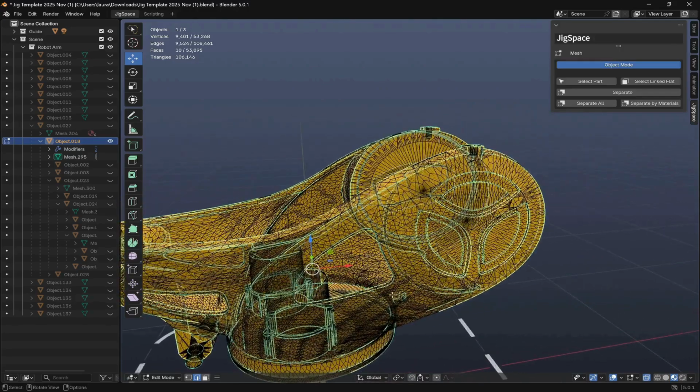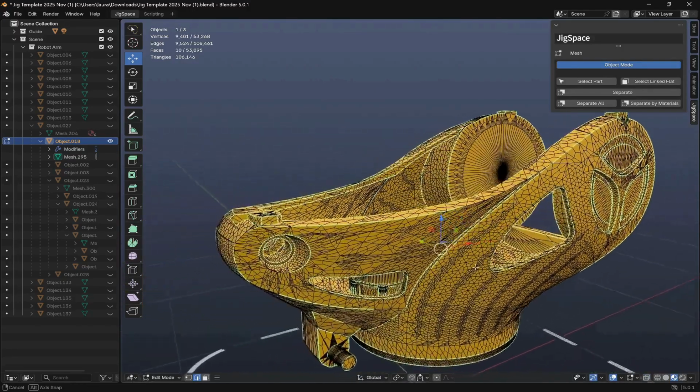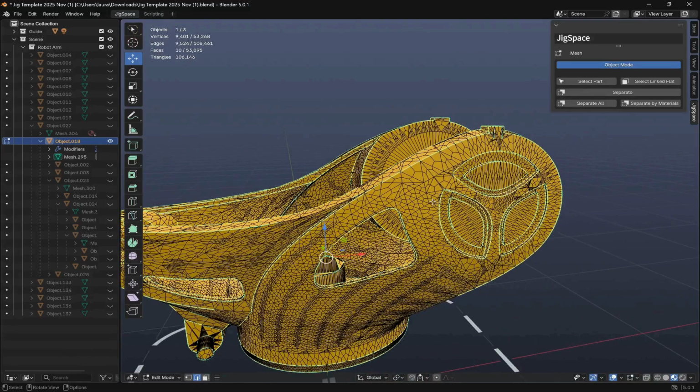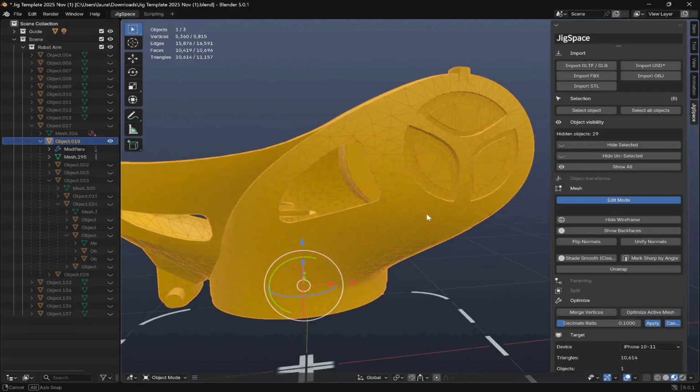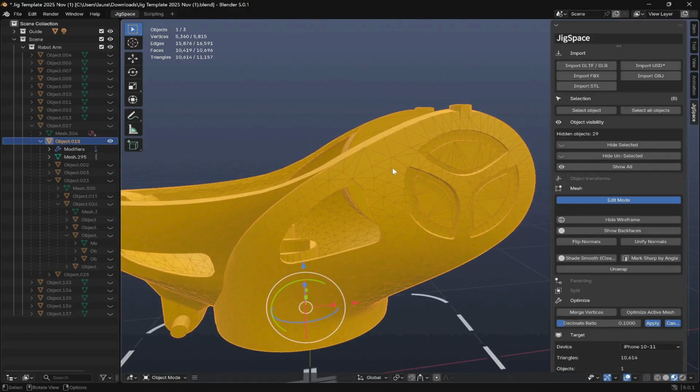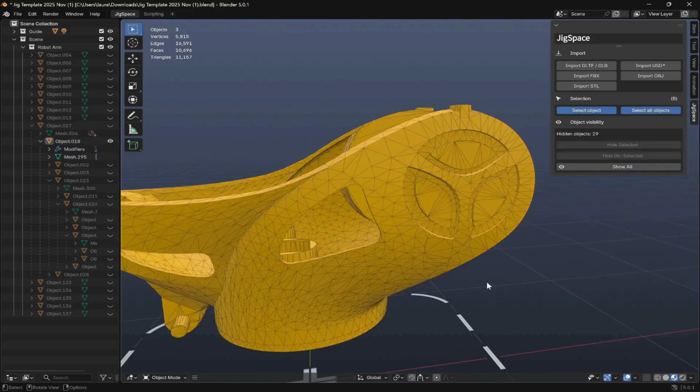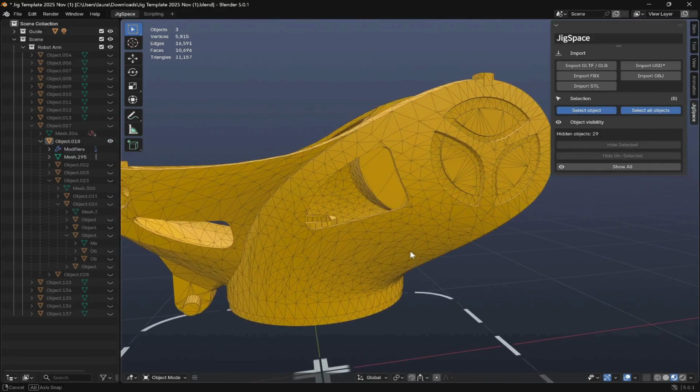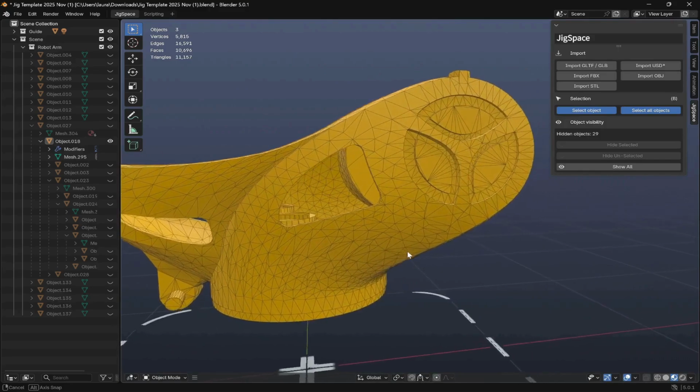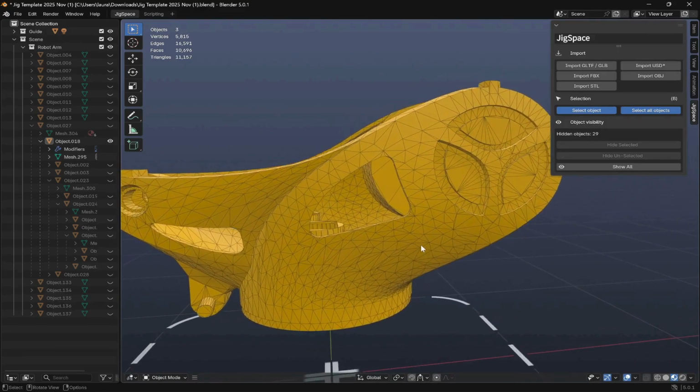And if you find it a bit distracting being able to look through the model, you can also choose to turn off that X-ray mode. So I'll click this here, and now I'm just seeing the front-facing edges of our 3D model. So if I press Tab to toggle between those two modes, you can see how our model is being affected by our decimation ratio. And it does look quite clean. It looks quite good. So I could use this as my decimate ratio.